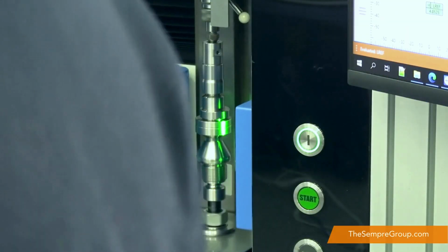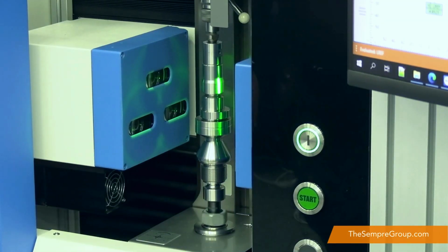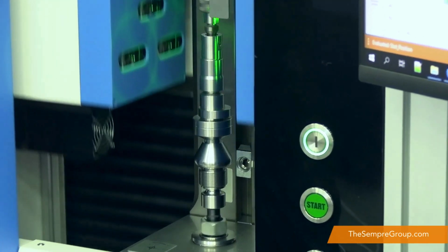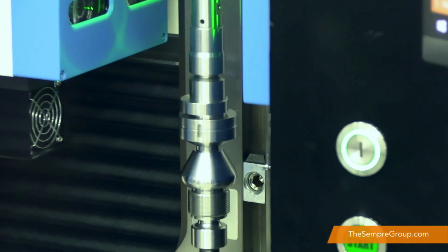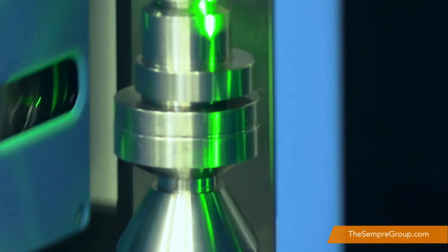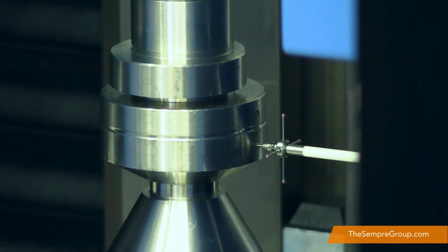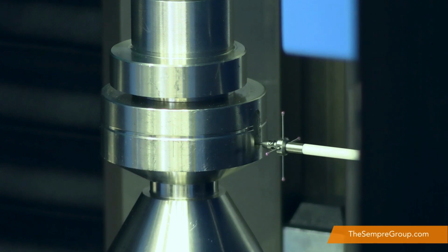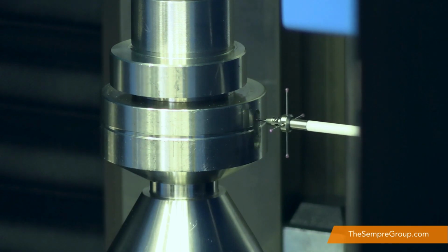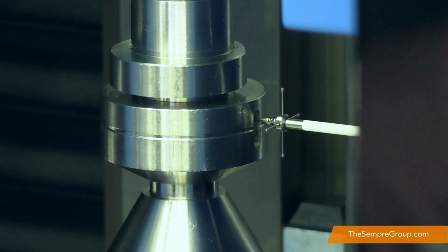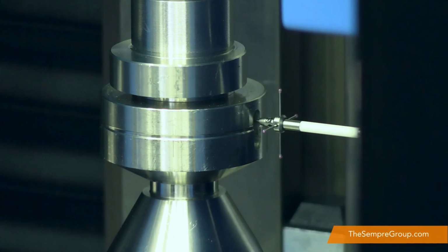Same principle again, we've got the length position being found, our A-ref rotational position, and then we're going to find the rotational position of the slot. The first measurement we're taking is on the flanks or the sidewalls of the slot, so we take 4 points in each position as well as 2 points on the bottom of the slot for the depth. You can see we've moved up to take our second level of points now.